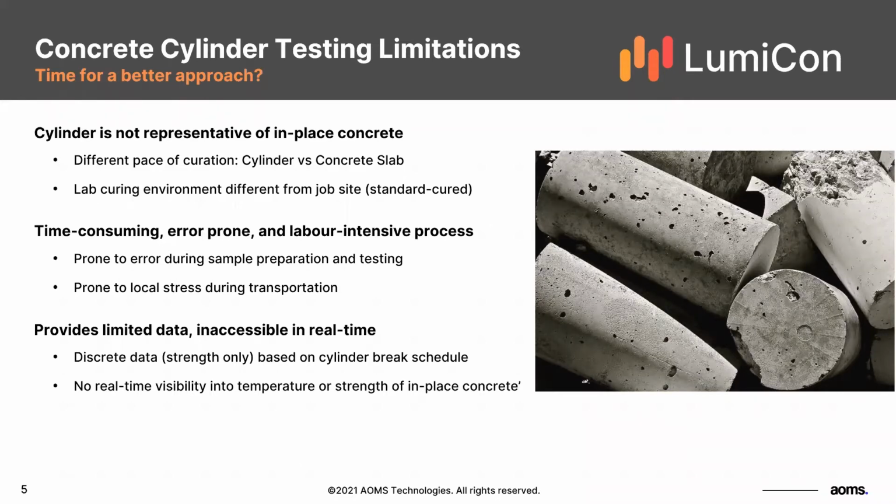Also, cylinders are being cured in the lab environment, and based on the ASTM standard, we usually put them at 23, 24, 25 degrees C. And again, that would create a different environment compared to the mass concrete, where the temperature can reach 50, 60, 70. Sometimes I've seen cases like in Hong Kong where it can get to temperatures beyond 90, 100 degrees C for the special design mixes that are used. So again, that would add to the uncertainty around how the cylinders could be a representation of the mass concrete.